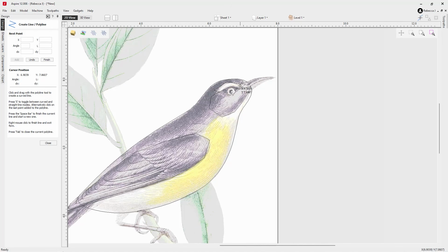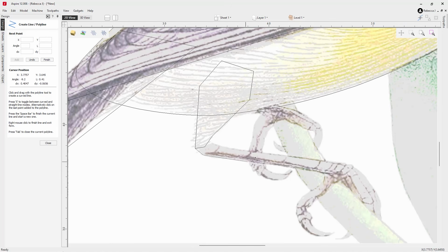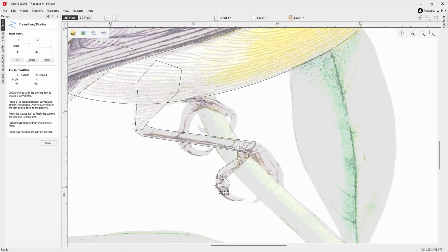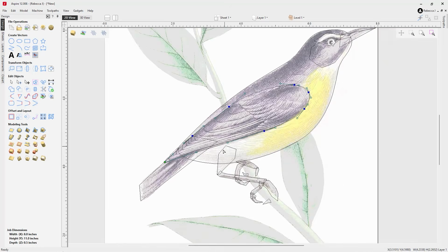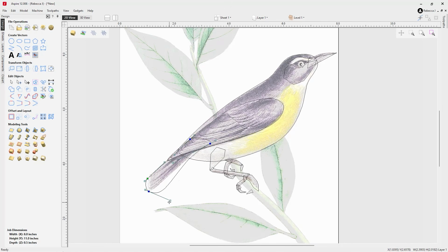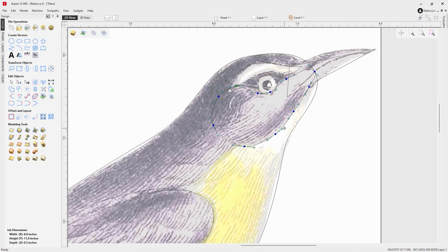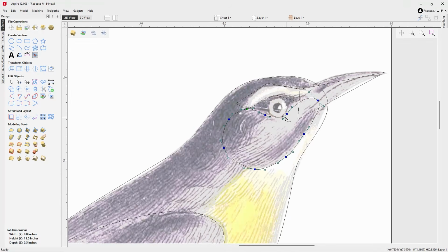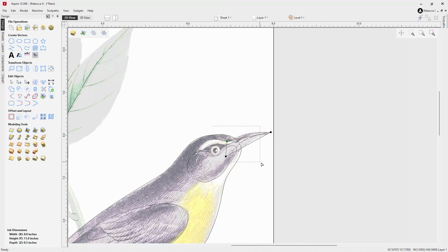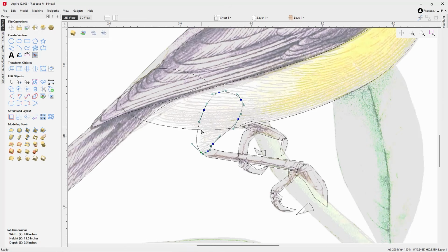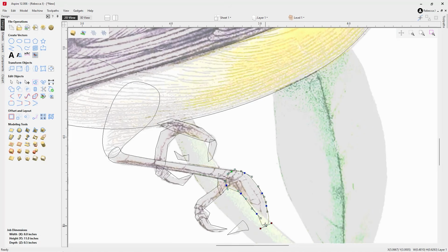So to start here, I'm just using the polyline tool to roughly draw out all of the shapes that we just spoke about, the joins for all of the different parts. And then going from there, I finesse those vectors, where I use the node editing tools to smooth out all of those harsh points to give us some really nice curves, and just twiddle with those handles to ensure that I get nice looking vectors.